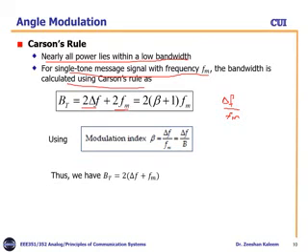It can be written generally by taking 2 common outside: 2 times delta F plus FM. So this was Carson's rule. By using this, we can find the bandwidth of a system. The other scenario, which needs more investigation, is ignored.